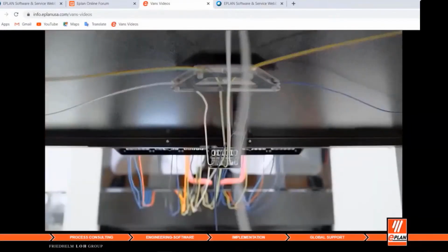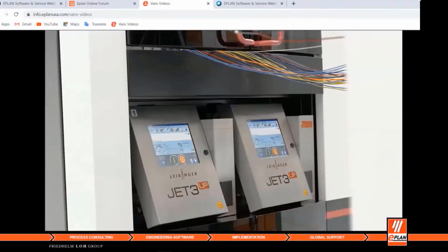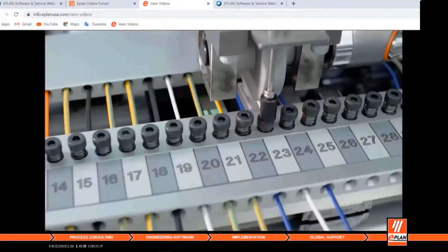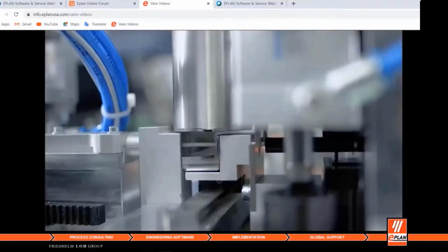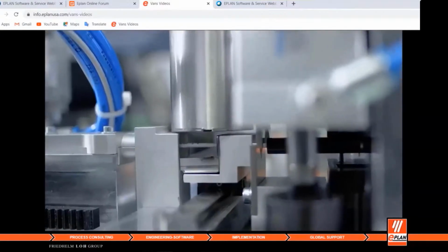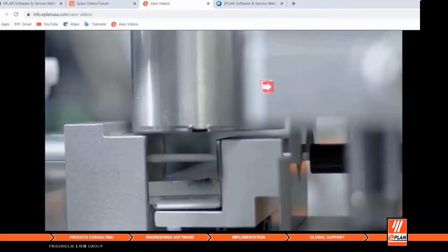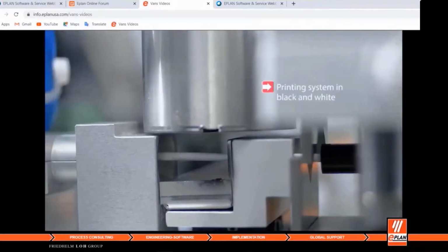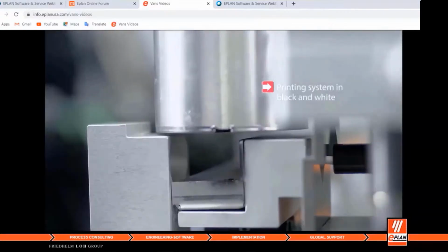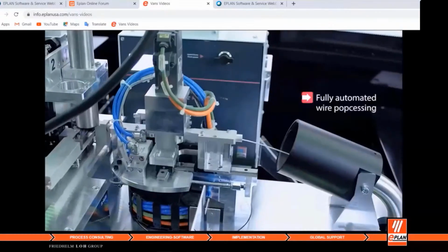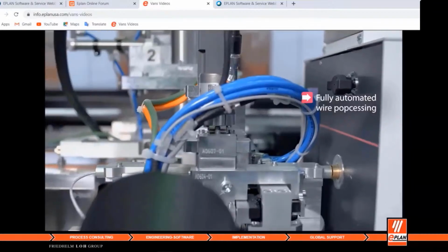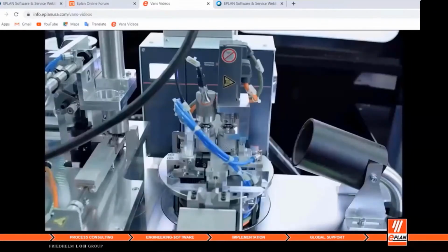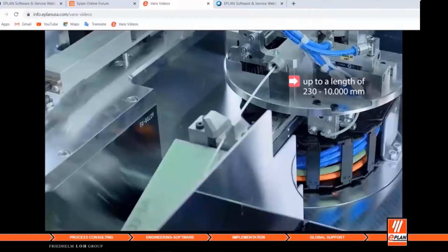We're working with essentially anywhere from 20 to 12 gauge in this process, and as the wire is fed in through that area, the comb up front, we are inkjet printing the wire. That means the to and from target source information, schematic wire number, etc., directly onto the wire, cutting it to length, and then stripping and crimping the ends automatically.